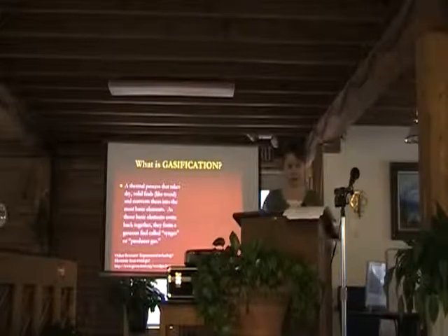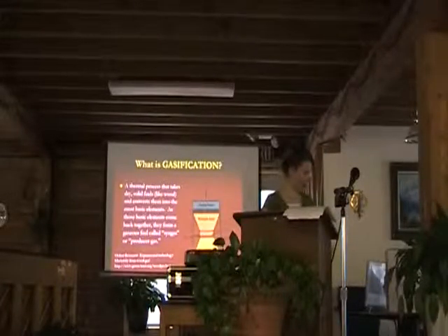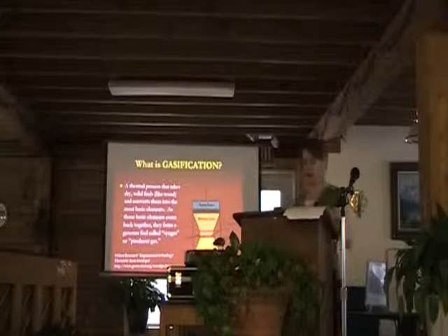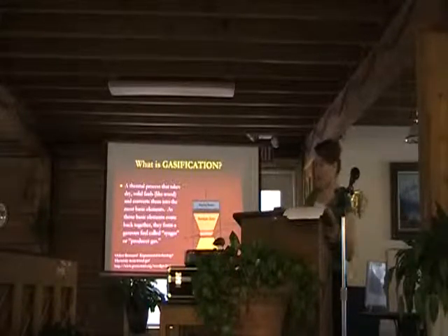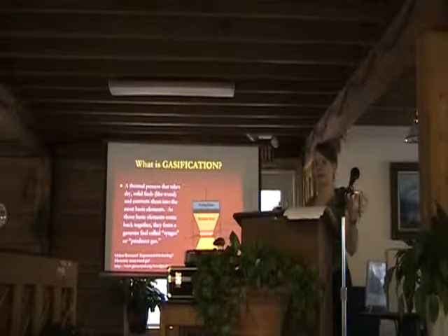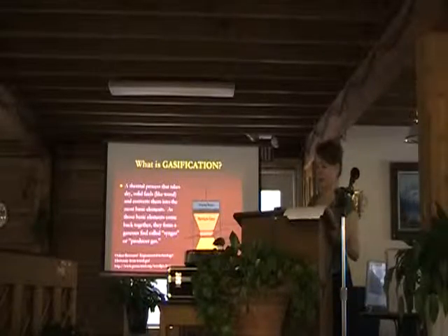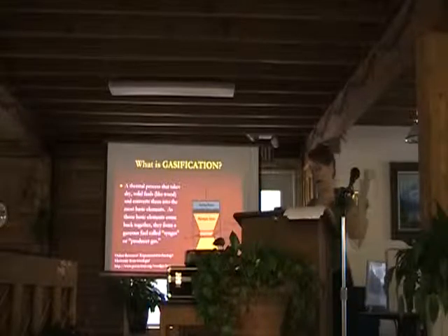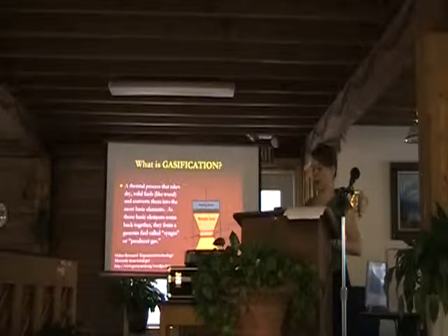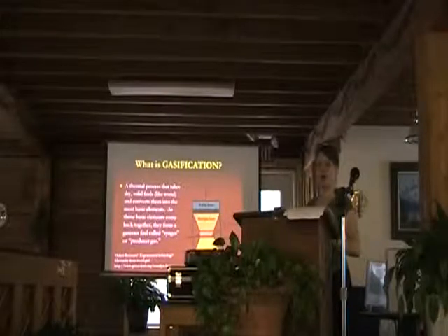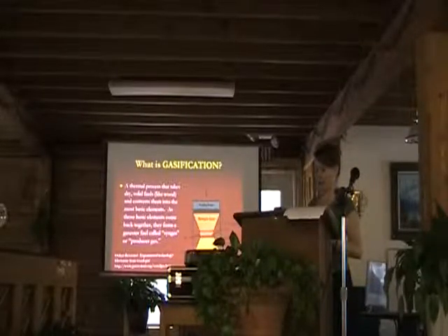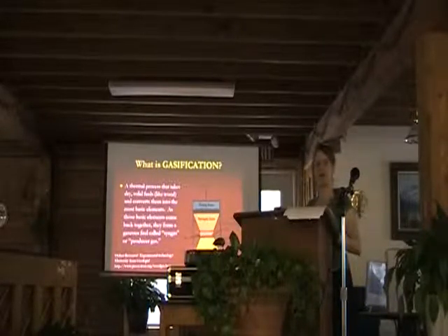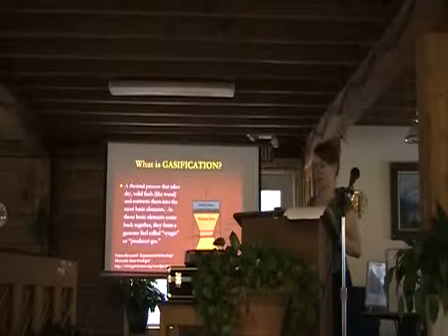That's all direct combustion. Here is a nice little diagram showing the process of the biomass feed, being the wood, that would come in, and of course the first thing that happens is a little bit of drying that takes place. And then we have the pyrolysis zone, the combustion, the air that's coming in to help that combustion out. Then it's reduced. All the gases are reduced. There's a grate there where all of the ash falls, and what is produced, what is the gas here that's being used is the syngas.